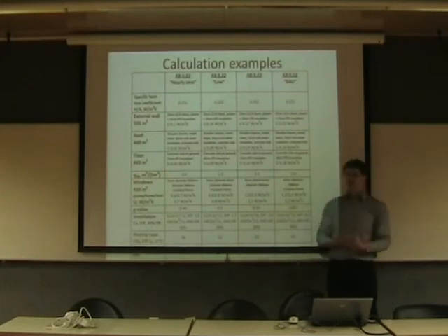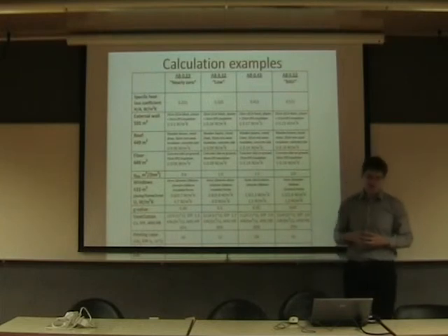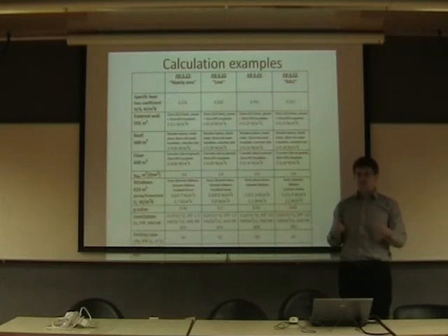With the degree days method, we can't calculate this cooling energy need, and then we can have overheating in the top part of the building, and this is one little problem.